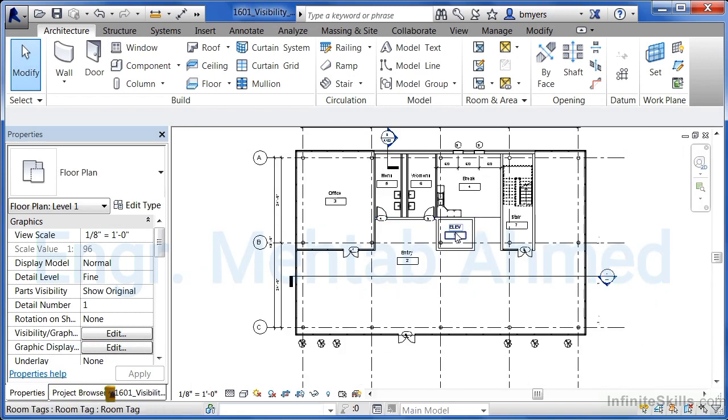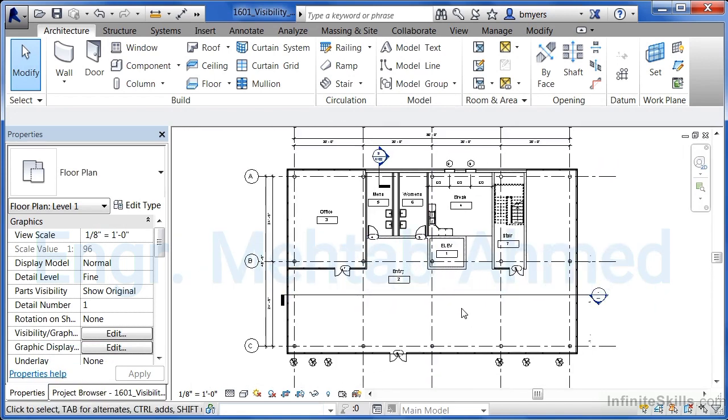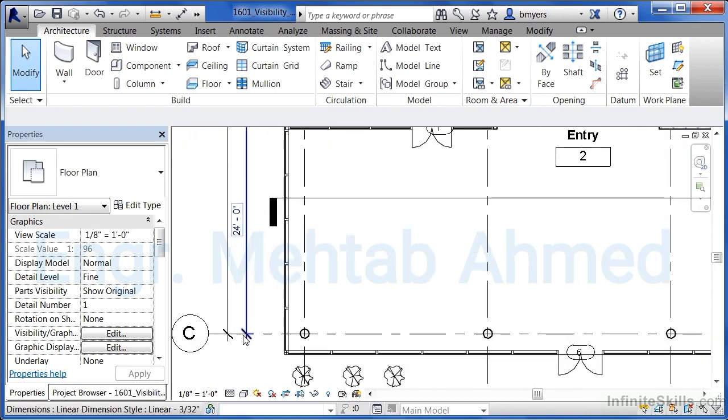Certain objects in Revit can actually have the colors of blue and green and red. You can give it any color that you want. So these do not have to be limited to being just the color of black like we've seen up to this point. Visibility graphics can assign those colors as well. Also, where we see the structural grids, this line style can be adjusted from being a center line to a hidden line to being a solid line through the visibility graphics and the properties underneath the visibility graphics for this type of object.